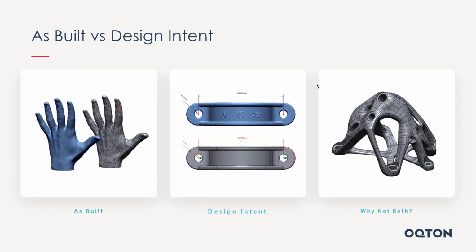So that will allow me to model around the part, pull the dimensions, and override them to be what they should be. That way, when I make another one, I'm not stacking the tolerances from when it was made before on top of the new tolerances of what it's going to take to make another one, right?